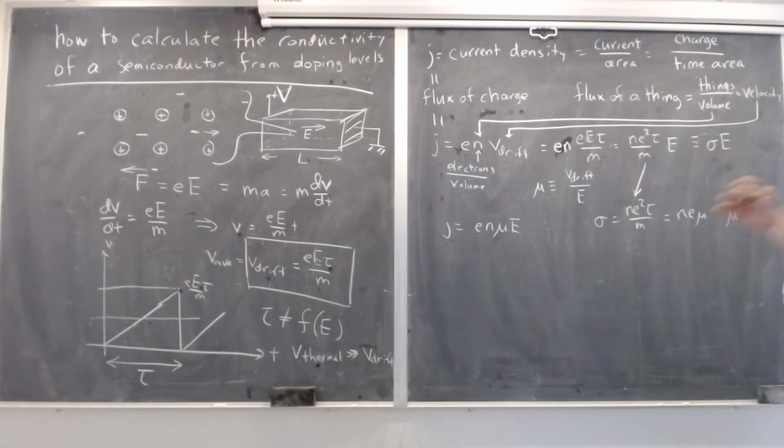So we've introduced this term mobility, and that's because for a semiconductor, mobility contains the ratio of tau over M, and so you don't need to know those things. To a certain extent, I just swept under the rug the whole thing about effective mass and all that stuff, and we can reserve that for semiconductor physics, for 446 and 646.